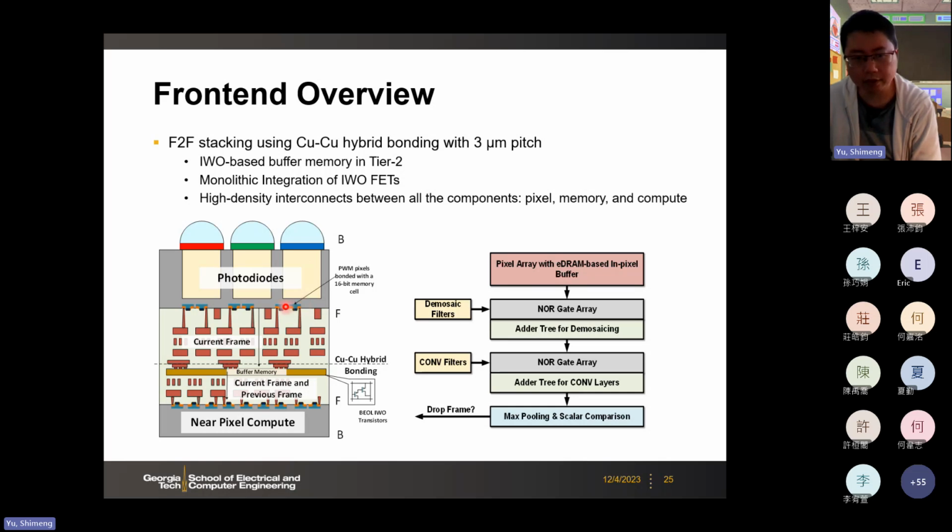And then through the transistor, you can digitize the current level, and then you convert that to the time pulse width, and then have the time counter to count the time window. Therefore, you can get the pixel value. So you have some circuitry here, pixel transistors to do this job. And after that, then you will have ADC to digitize that.